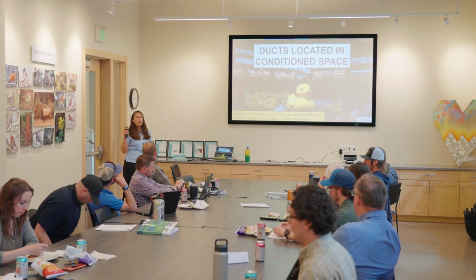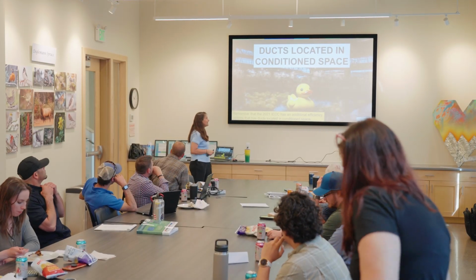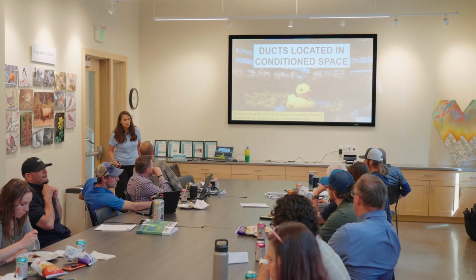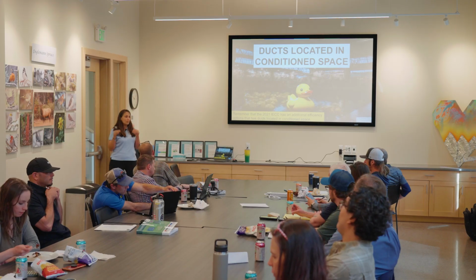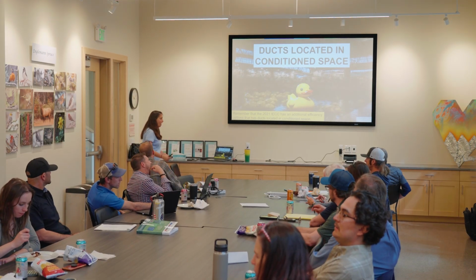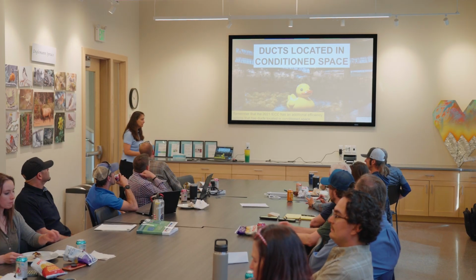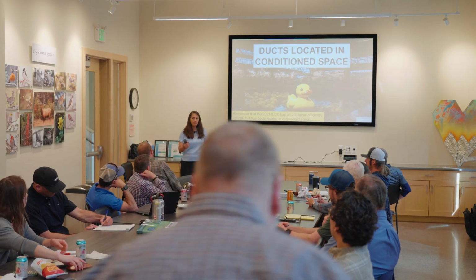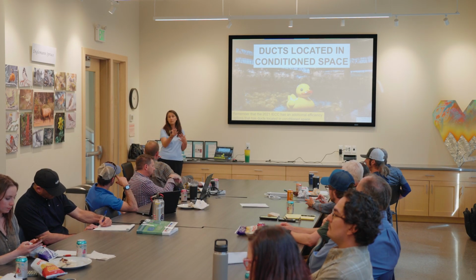So one of the items that you can choose from is having all of your ductwork located inside conditioned space. So we want to know how to get that ductwork inside conditioned space because there's a lot of things with it. But that means, are we only allowing ducts that are truly inside the thermal envelope as those being inside conditioned space? That's my question to you.